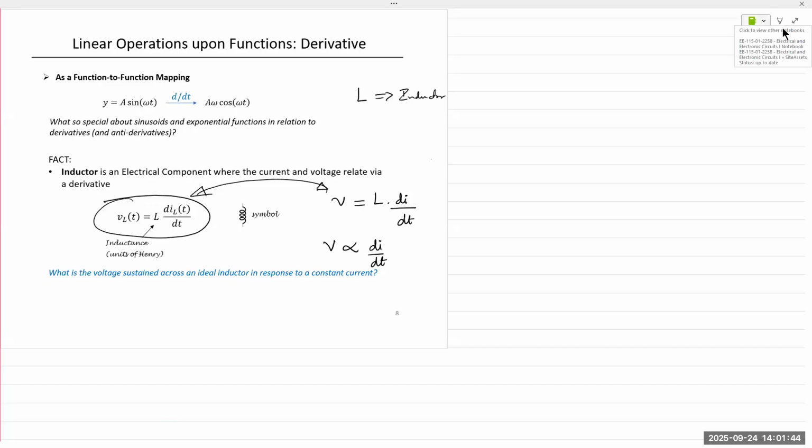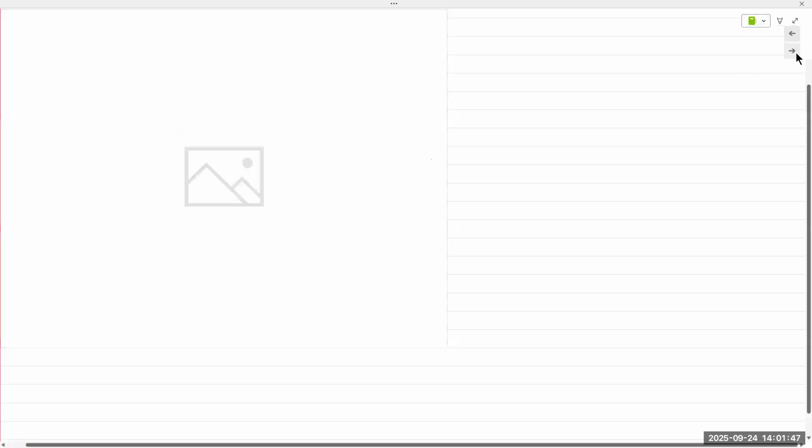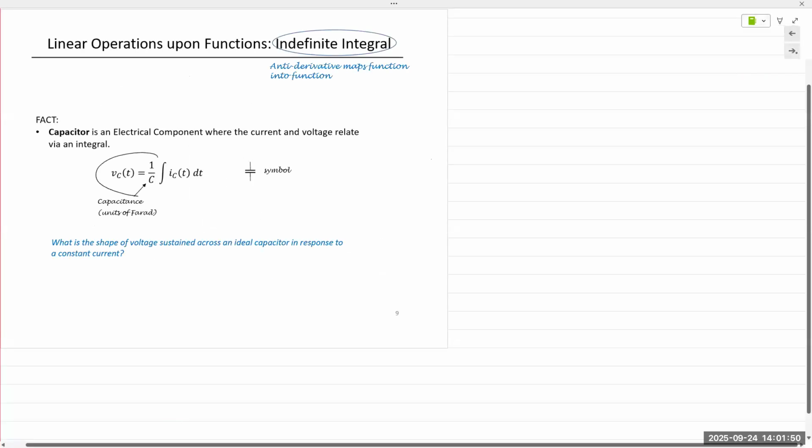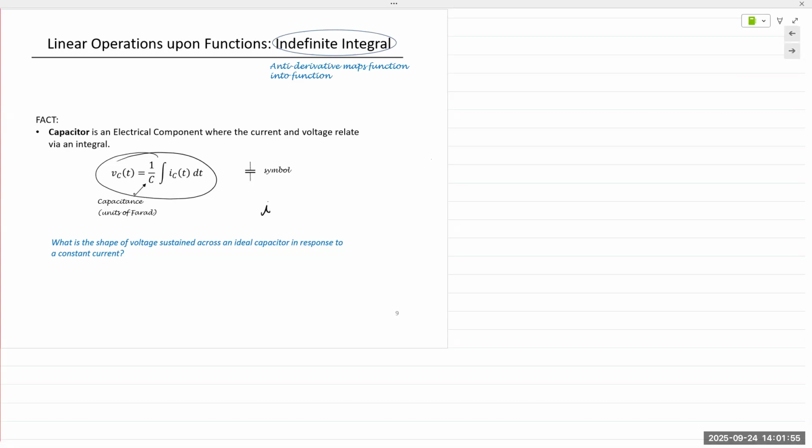And then finally, for a capacitor it's the same thing. For a capacitor, the equation is: capacitor current is equal to the capacitance times the derivative of the voltage. So I, current for a capacitor, is directly proportional to the derivative of the voltage. The constant of proportionality is the capacitance C. So I is C dV over dt.